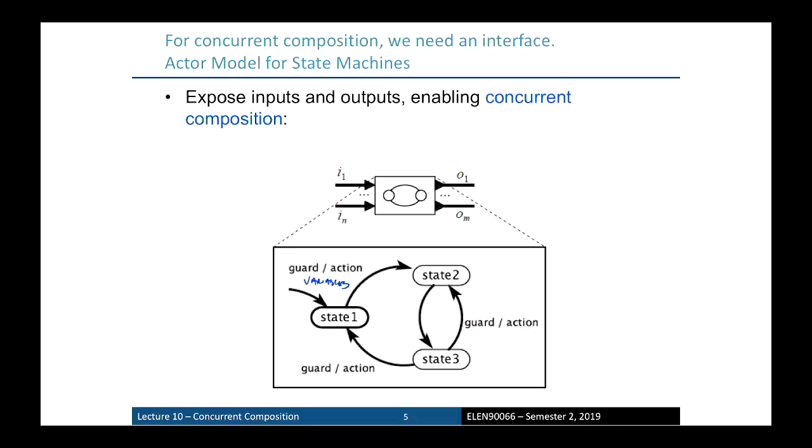A reaction happens on the inputs, and if some guards evaluate to true and the state that you move to has a different output, this happens straight away. There is no lagging of stuff going on. That's very important when we compose these things. We can't have these state machines with lagging stuff going on, connecting to another one, particularly in cascade, with a lagging thing. It gets very, very messy. We have no timing information about this anyway. So this little picture just says what it will do, but not when, with respect to some time basis.